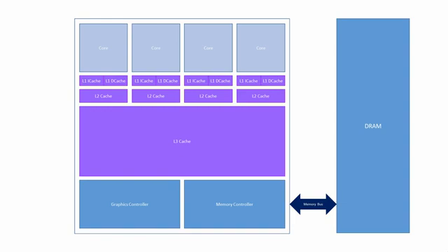Let's say, for example, a program instruction. The memory address of the next instruction to fetch is stored in a register called the program counter. The CPU checks the level 1 instruction cache first. If it finds what it's looking for, this is called a cache hit, and the instruction is copied into one of the CPU's registers.